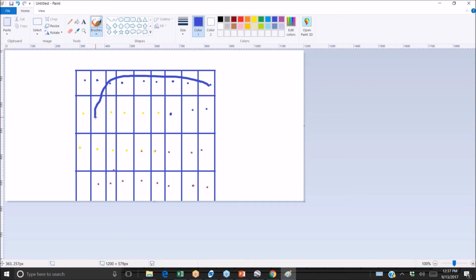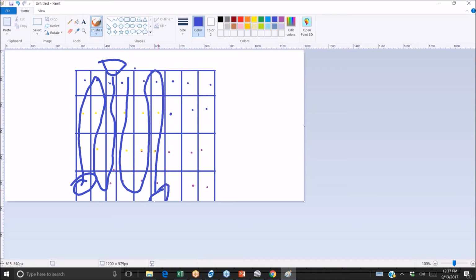If you're doing 12 modules a circuit, one circuit might be 1, 2, 3, 4, 5, or even better, you might go like that to put all of your circuits to be accessible along the edge of the array. So that's kind of a finer note: when I got into the industry, it was all about cost reduction. So you'd want to use the fewest number of circuits possible, because that meant less material and slightly more balance of system material savings.